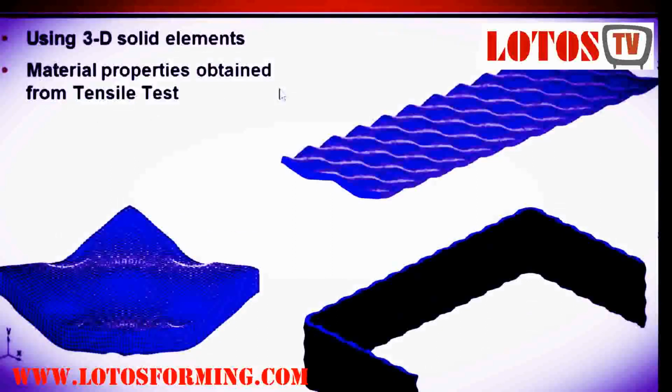And for the material properties for the dimple, in this case, we obtain them from tensile tests. So it means we perform a separate tensile test on the dimple strip, obtain the data, and then use that data in the simulation together with the geometry that we obtain from the dimpling process. We can do it for the small products, still using the 3D solid elements, like presented here.